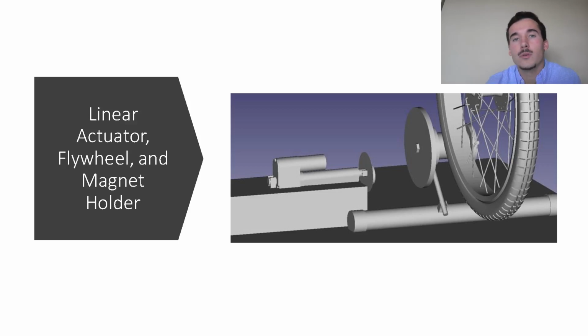So then we're going to go to our magnets and how they're being held. We're going to cut a circle that's 4 inches wide out of steel sheet metal. The reason we pick steel is so that the magnets can magnetize to the steel bracket. So if we have to add more magnets to the bracket later on, we can just move them around and we won't have to permanently put them on there. So it's not dead set on how we have to have our magnets placed. But if we have to permanently put our magnets on the steel, we would JB weld them so that they don't come off. And our magnets are going to be 2 inches by 1/2 inch thick.